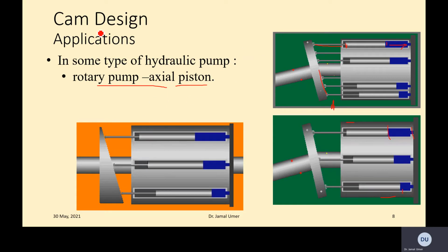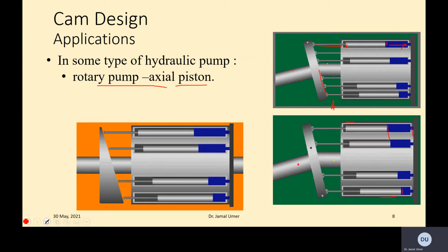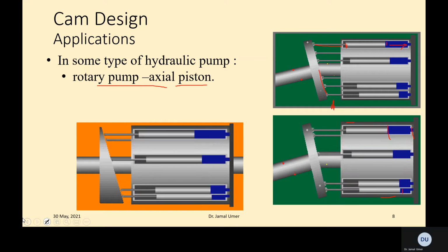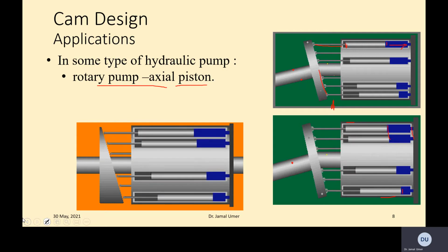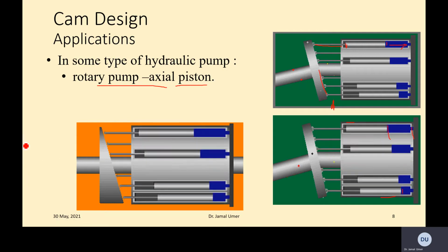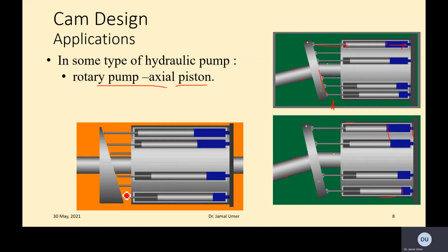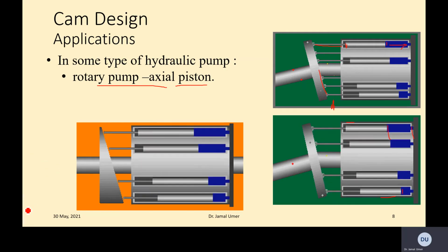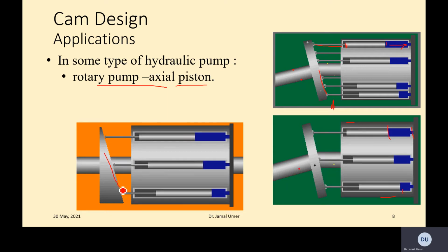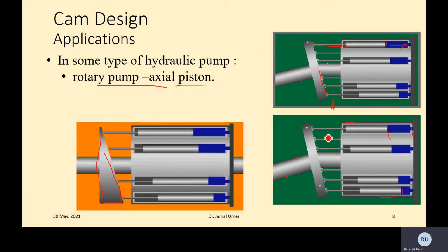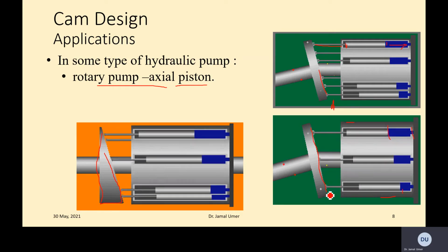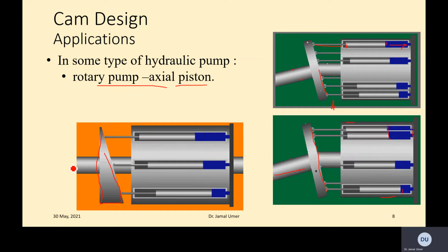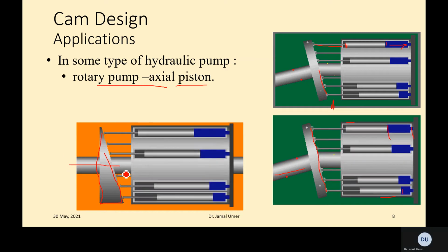So this axial pump, the axial piston rotary pump, is more like a higher flow rate oil you can provide using the axial piston rotary pump. So there are two different designs basically. There are two different versions here. We have the combination from here, which is like cam could be this design, or you have this inclined surface where you see here the shaft is at some certain angle, but here you have the shaft straight and axially.